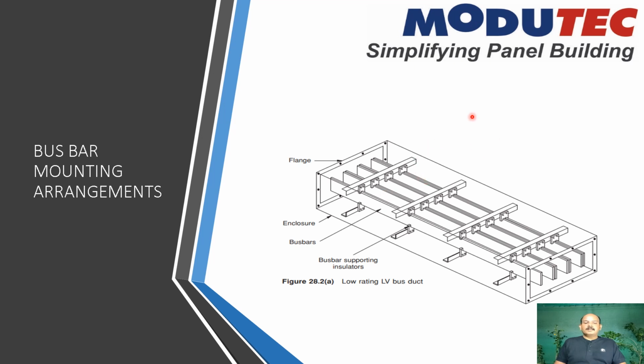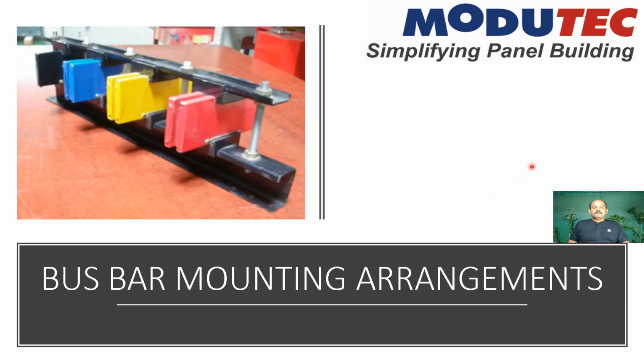Based on the K rating design, we choose this distance between the supports. This is one arrangement which Modutech normally uses. This is a G047. This black one is the insulator. On top of that is an MS support, bottom and top, with a full threaded rod in between, stainless steel, which we are using here.